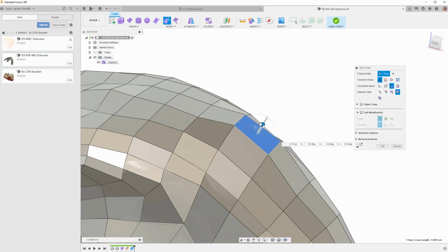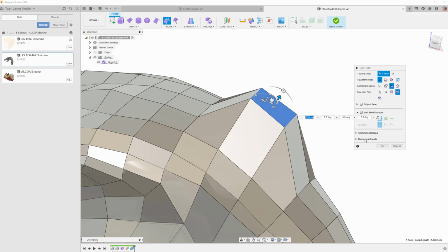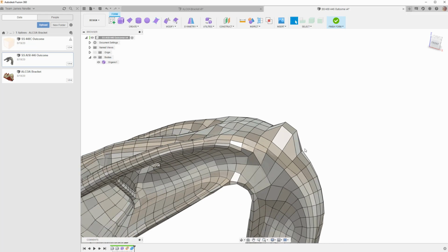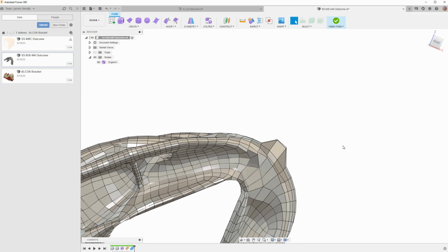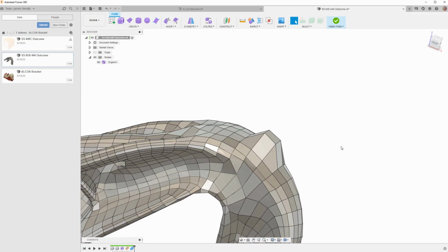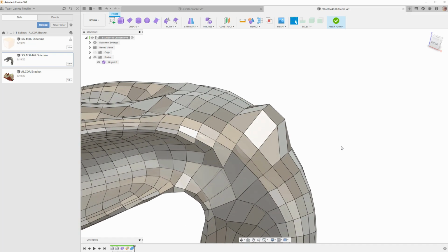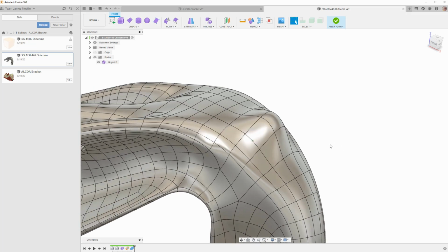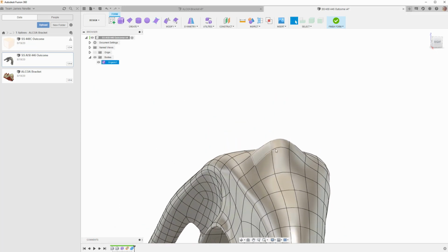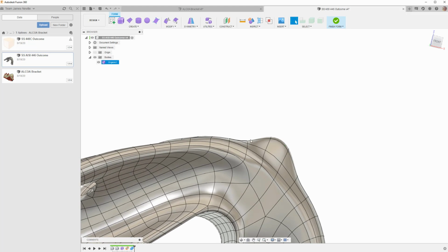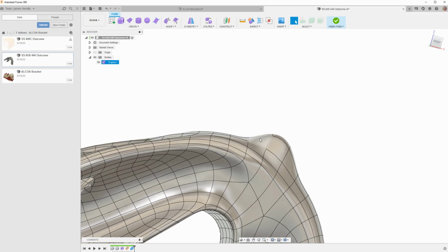Let me see if I can remember how. So I'm going to pull this up like, I don't know, 0.5 centimeters. Okay. Like that's not very smooth, right? And again, I'm in the box view mode, so it's probably going to get smoother when I go back to the smooth mode. Let's take a look. Go back to Alt-3. It's fine. Yeah, I mean, it's smooth, but you can see a little bit of an influence there, or a little bit of a transition there.